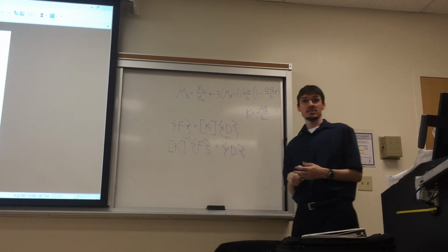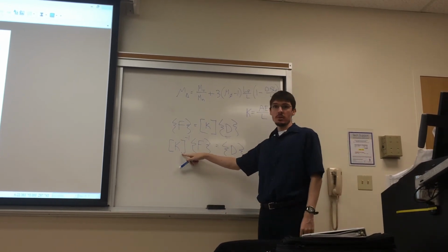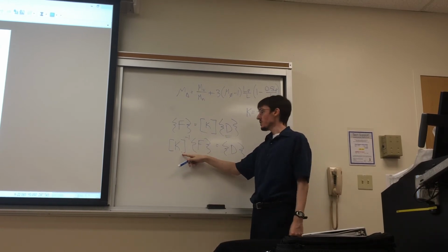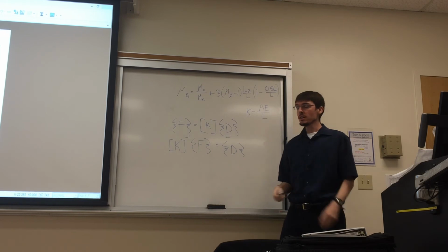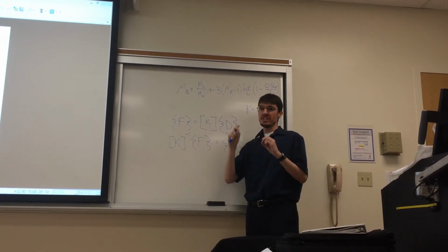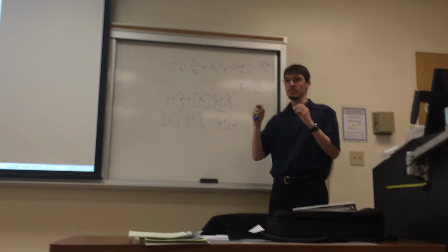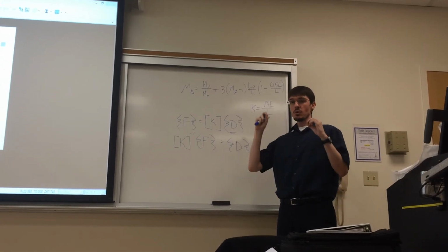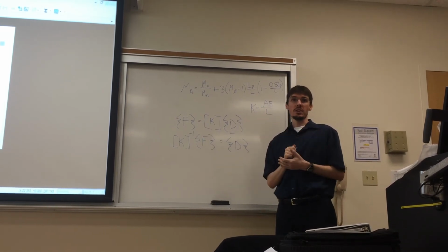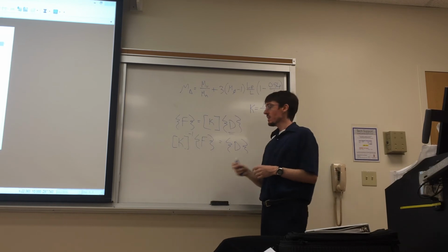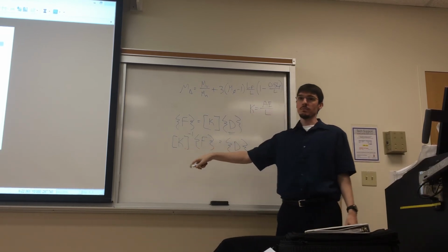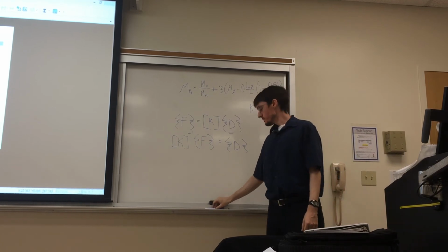The caveat in some cases is, this may be too soft for you. It may be inducing effects into your model that you don't want there. So oftentimes you'll hear, let's say, nonlinear analysis called an art. And the reason for that is you have to find a good balance of how do you change, let's say, stiffnesses of members that you're trying to fix in certain ways to give you a correct result without making them, let's say, too soft or too stiff. Because if they're too soft, they're actually influencing numbers a lot. If they're too stiff, you can't actually get a solution. There's a fine balance to be had there.